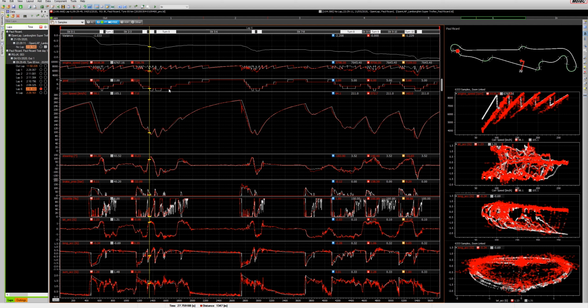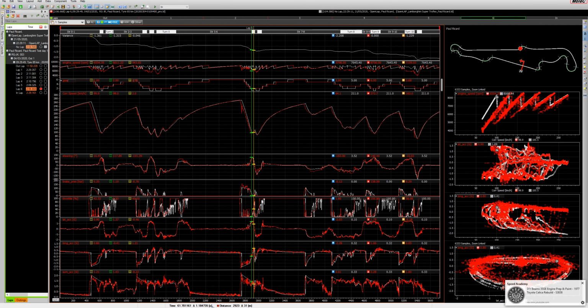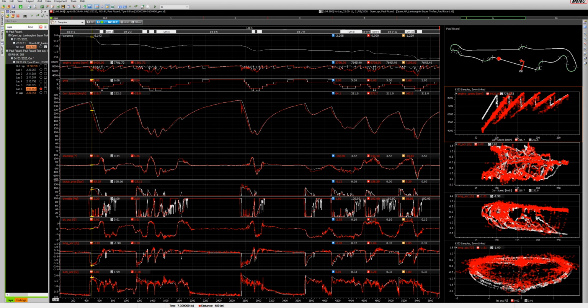Also, we don't model the gear shift duration. So a selection of a gear for 1.2 seconds doesn't actually make sense in reality. In terms of RPM, it's better to look at this graph over here, where we actually have the RPM versus the corrected speed. Obviously, we have white points here in this region just because OpenLAP selects the first gear sometimes. But in general, the slope of each gear is correct.